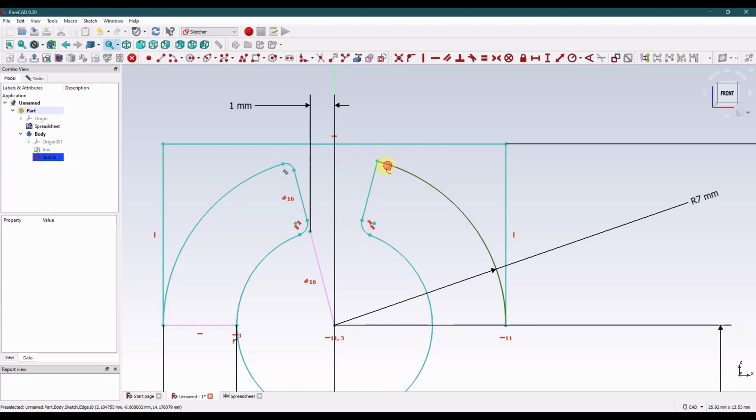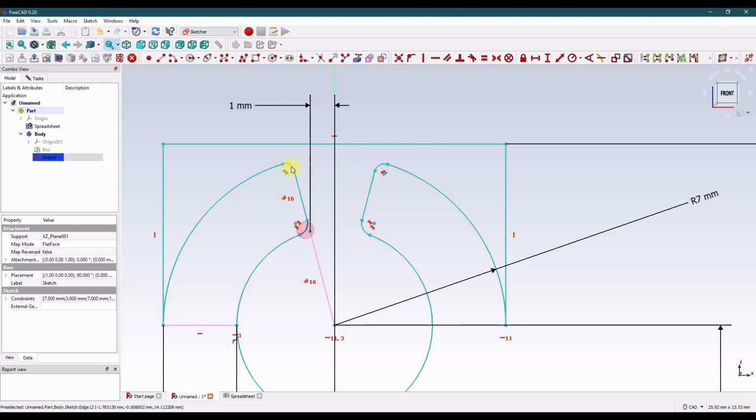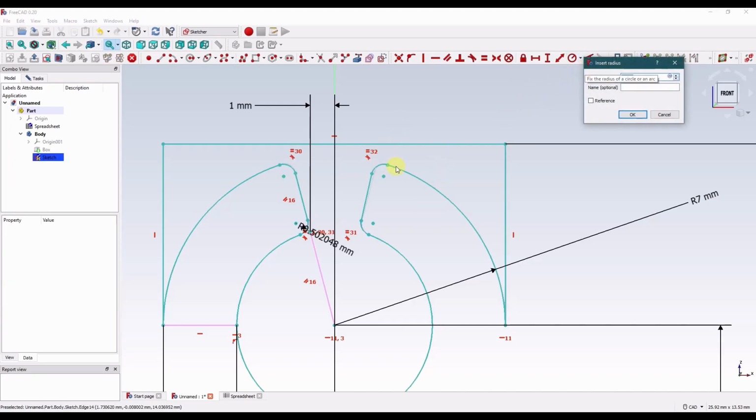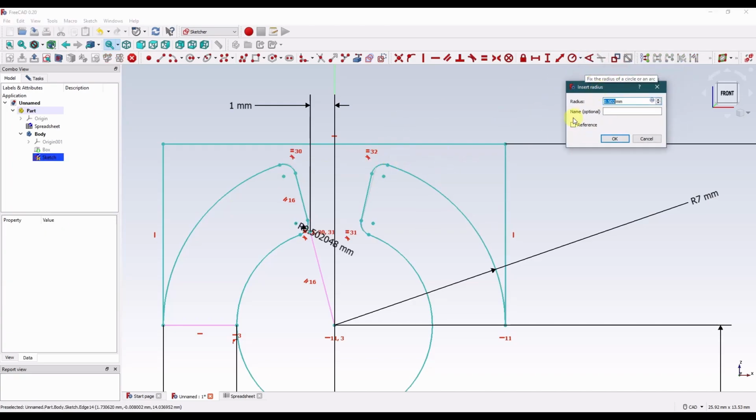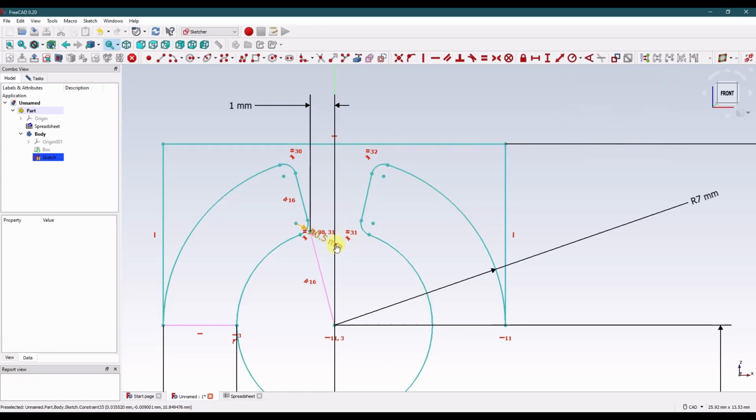So I forgot to add those. No problem, we can add all of these references back in. Selecting all of the fillets at once and then setting a radius, we'll set them all equal. And I'll make it, 0.5 is okay.